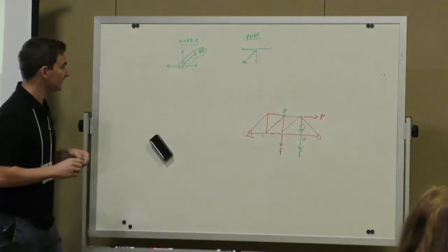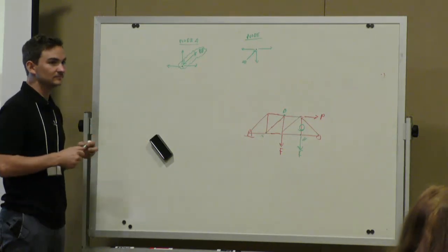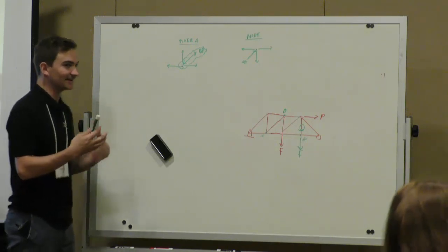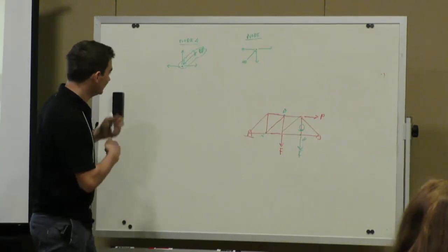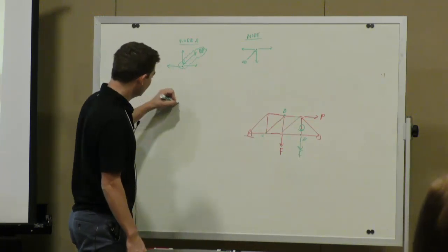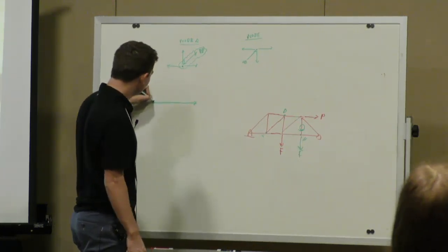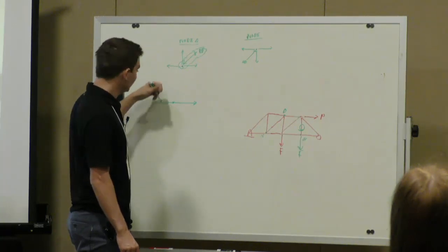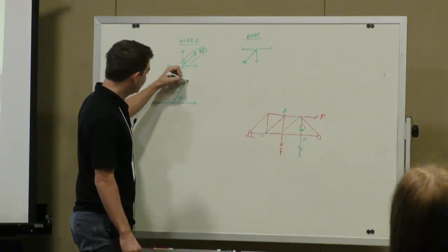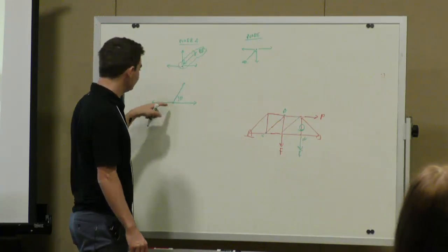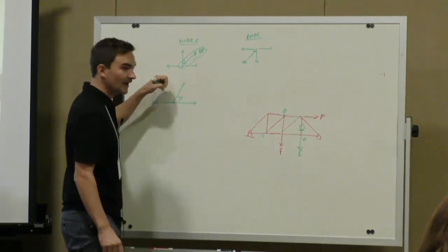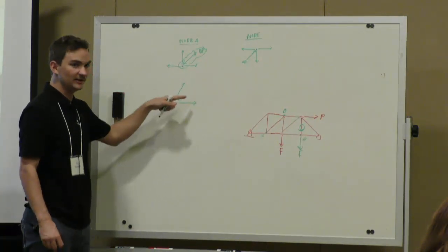Yes, very good. Could you just state the rules for zero force members? Yeah, I can go over them. I don't have the exact wording memorized, but I know the rules. I believe one of them was if you have two bars that are collinear, and you have one acting at some angle theta, so it's a three-member joint, with two collinear and one acting at some angle theta, then the one acting out of the line of those two would be a zero force member.